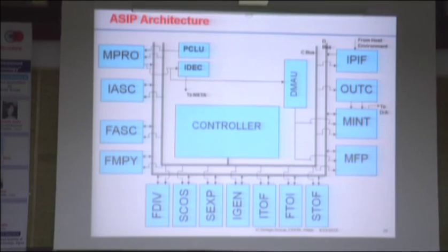So generally there are three kinds of implementation available for a control. कंट्रोल को इम्प्लीमेंट करने के लिए तीन तरह के ऑप्शंस रहते हैं. एक होता है आपका हार्डवायर्ड, तुमने पढ़ा है सब मोरिस मैनों में, हार्डवायर्ड अप्रोच और आल्सो कॉल्ड रैंडम लॉजिक इम्प्लीमेंटेशन. There you implement the control using logic gates. The second approach available to implement the control is the micro-coded approach, where you store all the controls in a memory or in a ROM, and then you fetch the necessary controls to supply to the associated blocks in the microarchitecture.